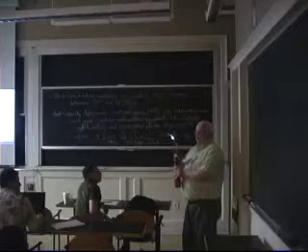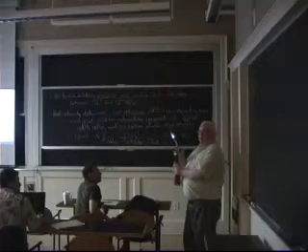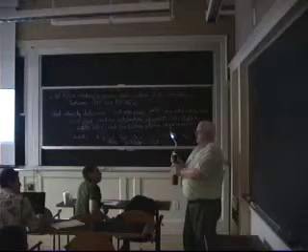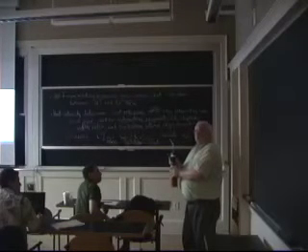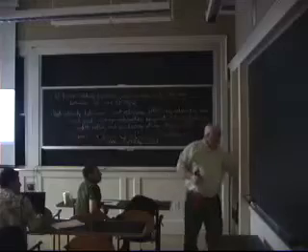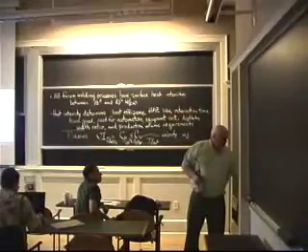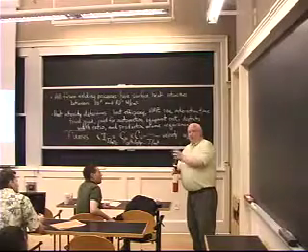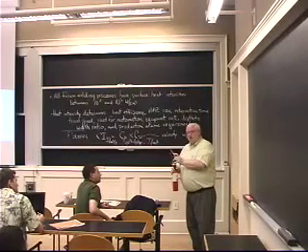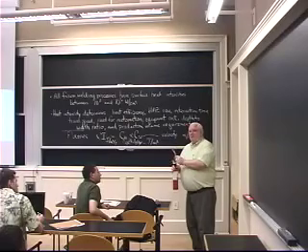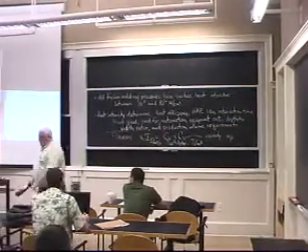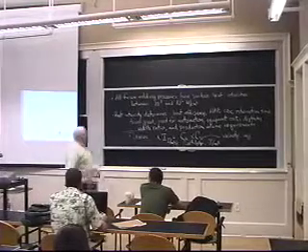In fact, if I turn this off, if you look right down here where I'm mixing the gas with the air, these little holes down here, you should see a little flash. You see the little flash? That's because when I turn it off, the velocity of the gas coming out has to go to 0, and the combustion velocity now exceeds it, and it burns back to where the gas was coming out. And you saw the little pop there at the end, which will always happen. It's an experiment that usually doesn't fail.